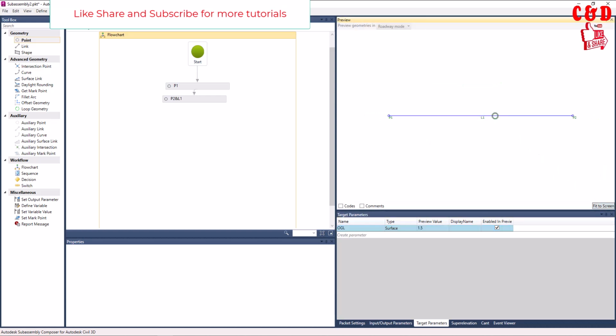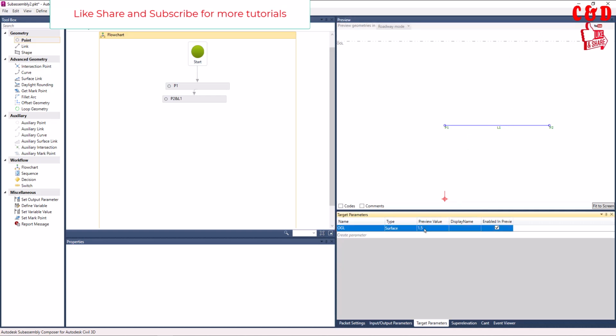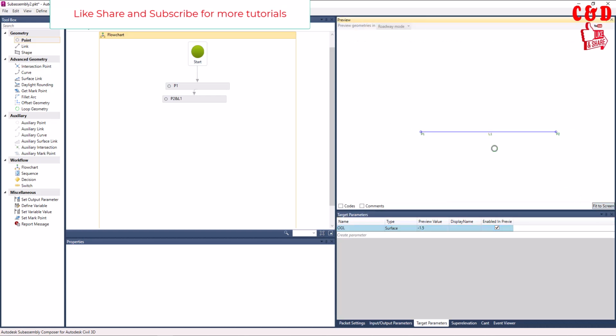Okay, you see, when you put a positive value it goes above, but we need below. OGL is below the retaining wall top, right? So 1.5 should be a negative value. Now you see it is below here. Now we want a line from P2 that targets this location, and then we can determine the point and how much we have to go down from this particular OGL.